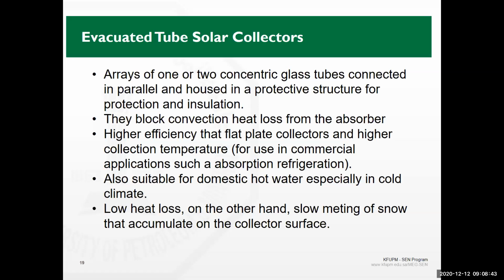We expect higher efficiency, especially at high temperature. They do not lose the energy easily. Flat plate collectors are basically receiving thermal energy. They have very high efficiency, but the efficiency gets less quickly as the temperature difference increases, which is not the same as evacuated tube collectors. We'll see a figure now that's going to show that.